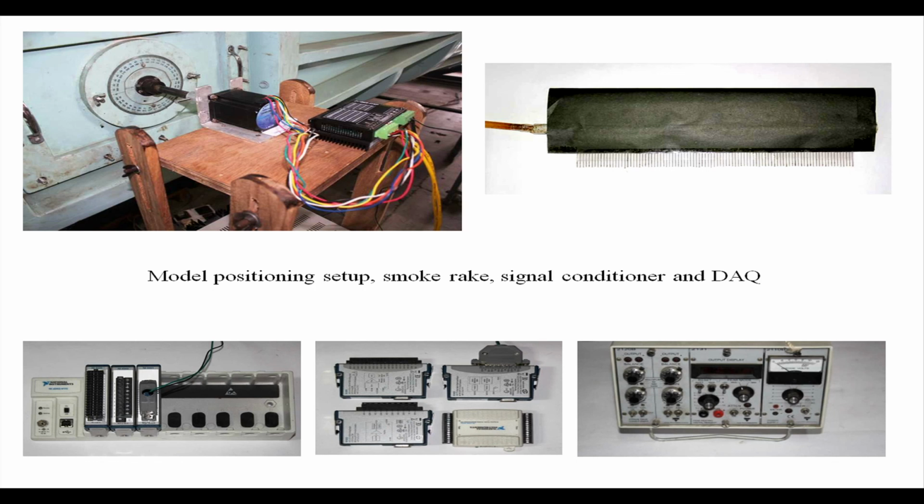Flow separation can very often lead to unsteadiness in the flow. I will talk about it in a little more detail later, with some pictures also showing you flow features which will appear quite unsteady. And therefore, if you are say holding the model at a fairly large angle of attack, what will happen is the pressure from one port to the other, if you record it over a period of time, you will see variations coming up. But the same airfoil at a fairly low angle of attack will not show significant time variation.